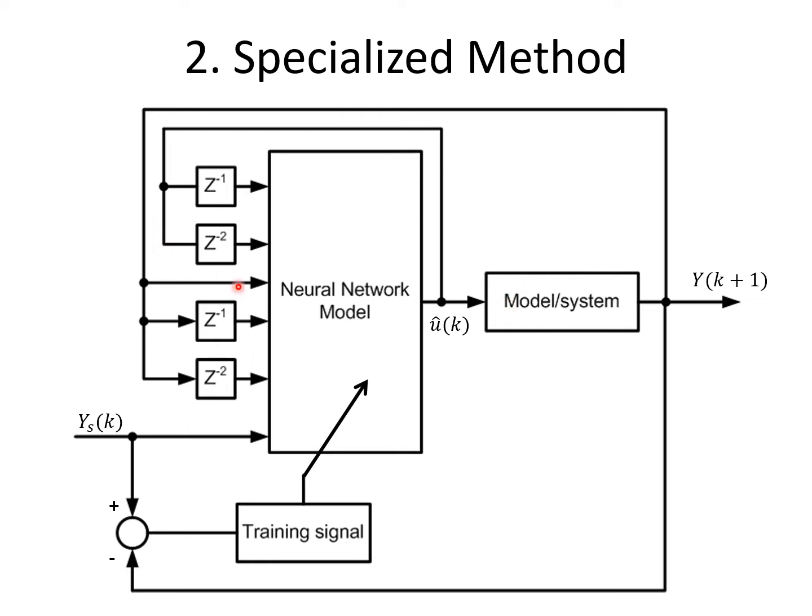So when we train the neural network using the back propagation, we have to slightly modify it to cater also for the gradient for change between U and YK. The gradient in the system has to be incorporated in the training algorithm so that it is trained based on whatever YK it is, not on U but on YK.